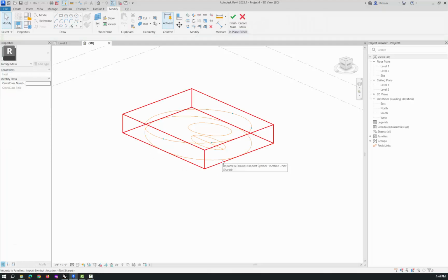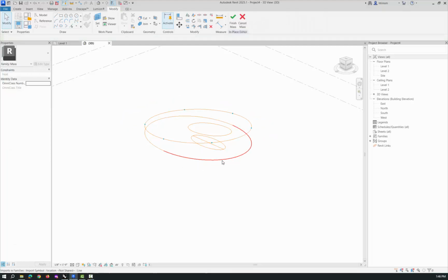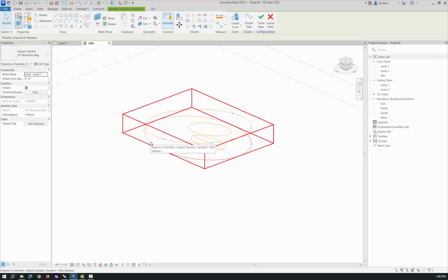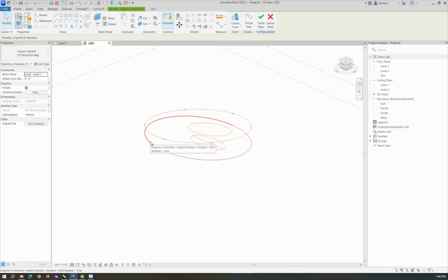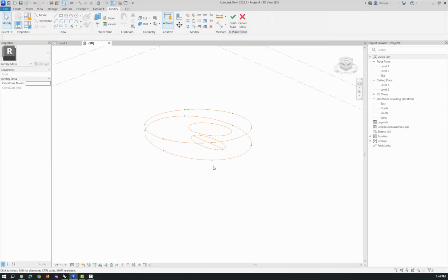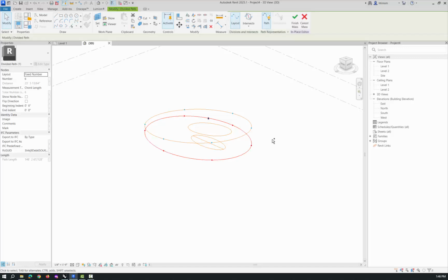Do the same thing to the bottom one. So tab, left click, hover, tab, hold down the control key, left click, and divide the path. So now I've got 2 divisions on these guys. And I want more, these are where our columns are going to go, and I want more divisions on it. So if I come in and pick that divide and hold down the control key and pick the other divide, I can actually put a little parameter on it that will allow me to change those divisions at the same time instead of having to do them individually.